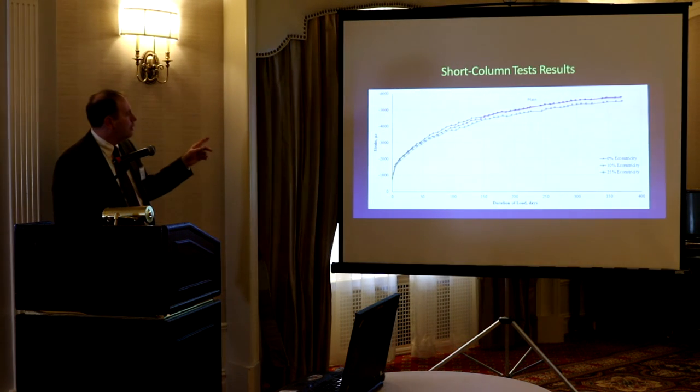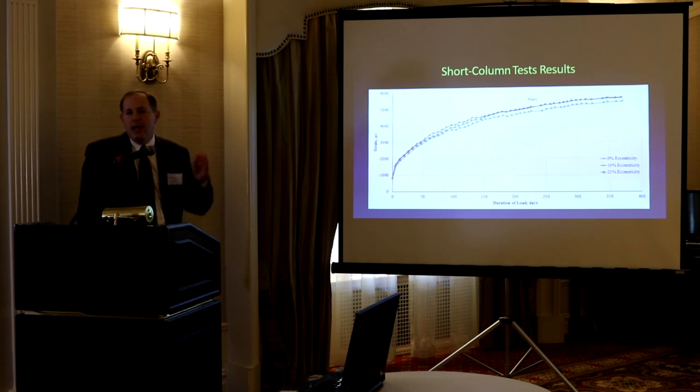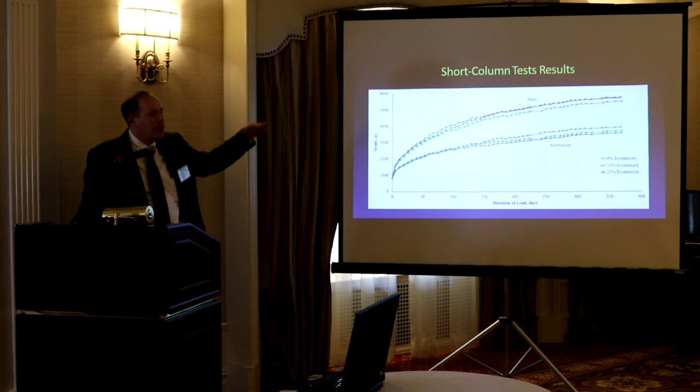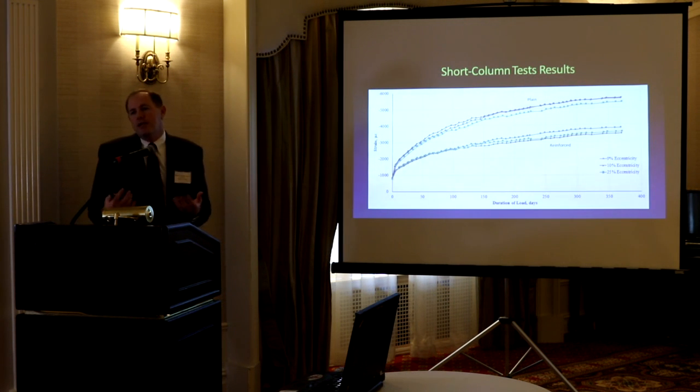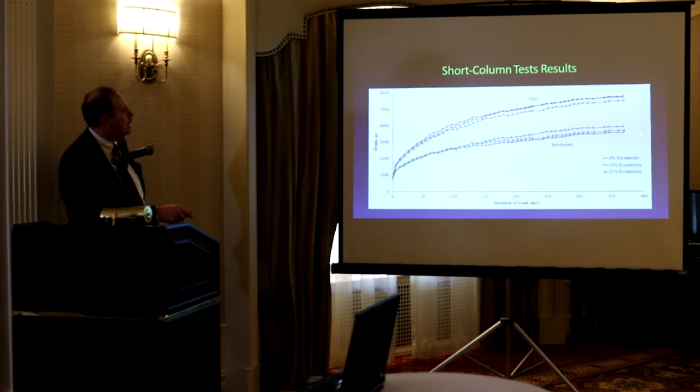So if I take a look at that, this is plain columns. These three different eccentricities followed pretty well. The creep did, at 50%, holding that, it worked pretty well. Here's reinforced. It's going to break down your strain because the steel is taking, right? The steel is shedding. The concrete's shedding load into that steel. And so you see the reduction here.